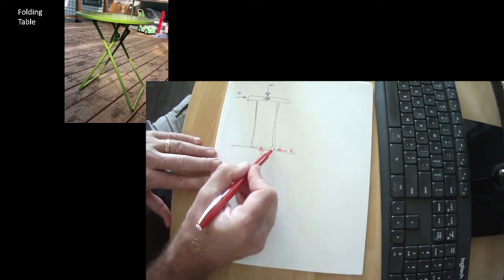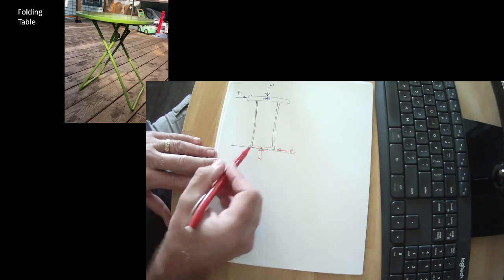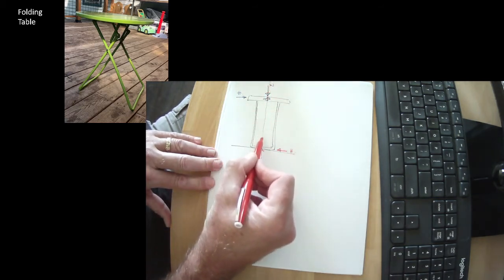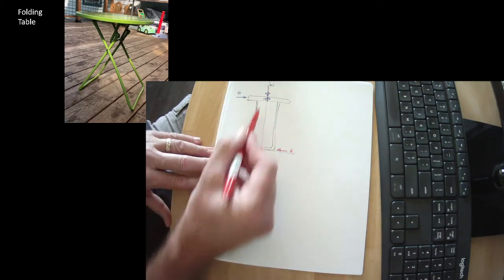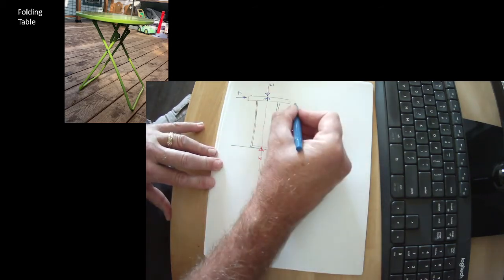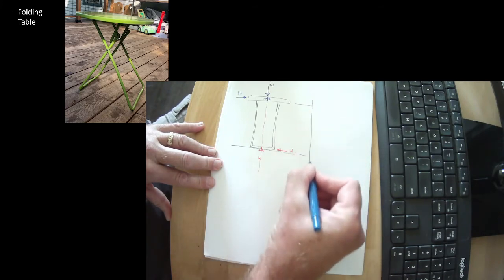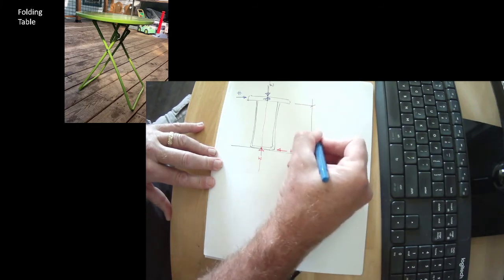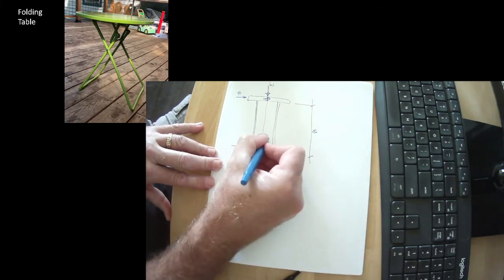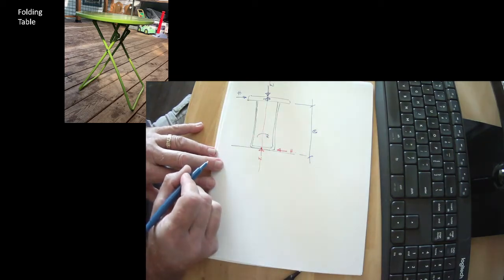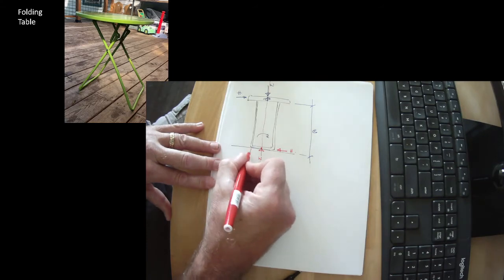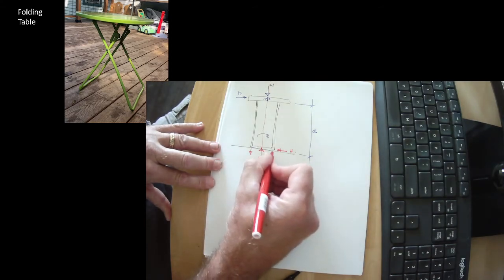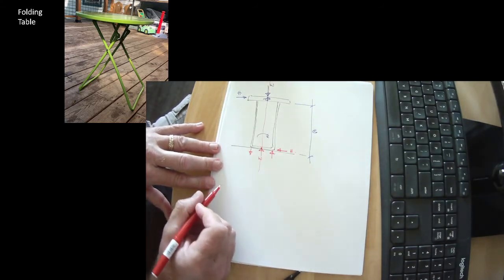That's a resultant because that's not a discrete point, but we know that the weight has to get resisted by a resultant underneath the weight. We know that the wind is eccentric, which tends to create some overturning this way, which means that the wind gets resisted by a couple, like that.